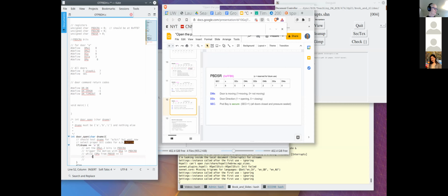In the language of Arduino, we will delay for maybe, let's say 500 milliseconds, half of a second. It's about 10 seconds, we said, to completely open the door. So that'll get us within 5% of the maximum wasted time. And then we'll check the status.